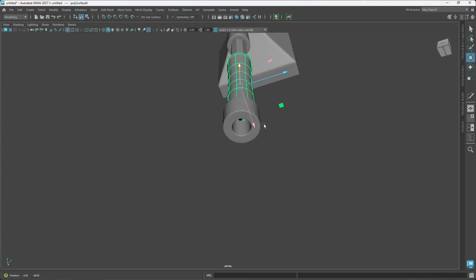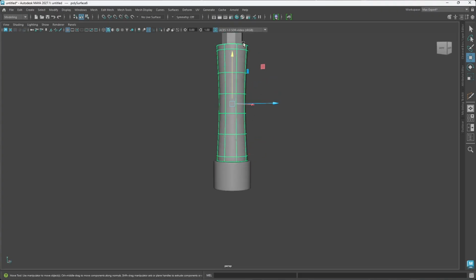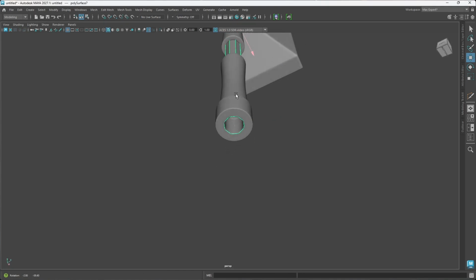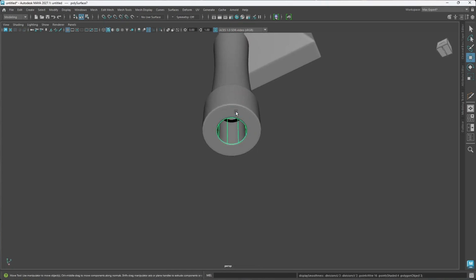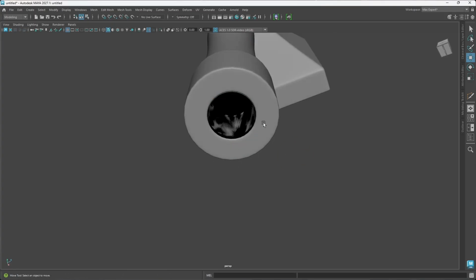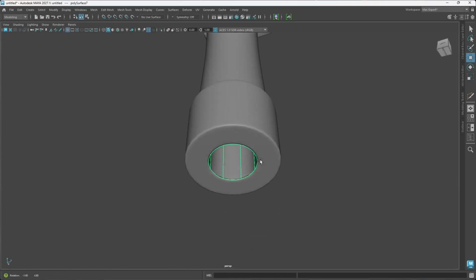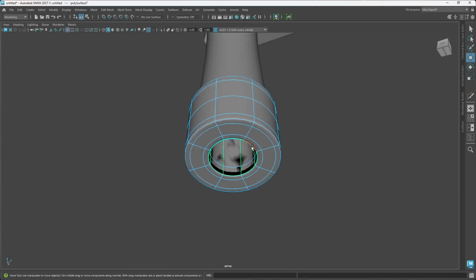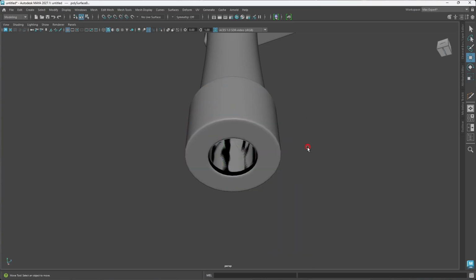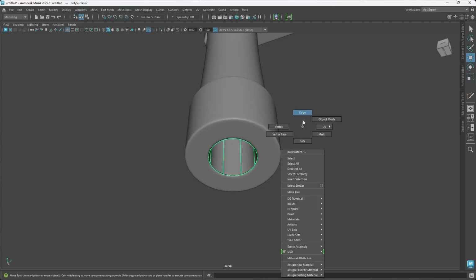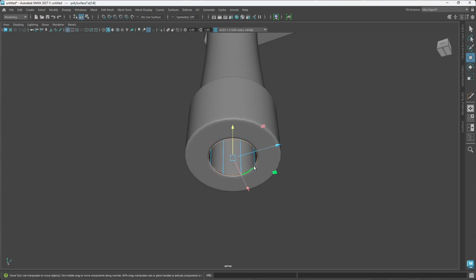On top of that, now we can select this, hit 3, and now the smile we were smiling before is actually going to end. So we can select this, right click, go into the edge mode, and let's go back into the object mode, select this, edge mode, select the smooth round, hit 1, and now we're going to hit R, bring this inward.